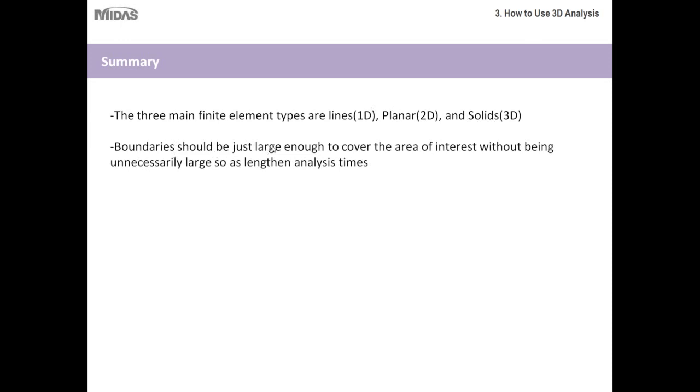Then, boundaries should be just large enough to cover the area of interest without being unnecessarily large so as to lengthen analysis times. Keep in mind that the larger your project model is, the longer your analysis will take. But you also want to make sure that your model is still large enough to cover all of your necessary boundaries, so that all of your strains and displacements, all of your results are within the size of your project. To start off, it's good to use the examples that I showed you as a reference.